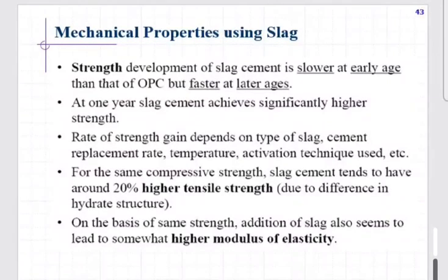So 0.003 strain. But that is its ultimate strain, where concrete fails. I am talking about the elastic strain. Sir, slope of the stress-strain curve up to 40% of stress. You can say this is one way of doing it.